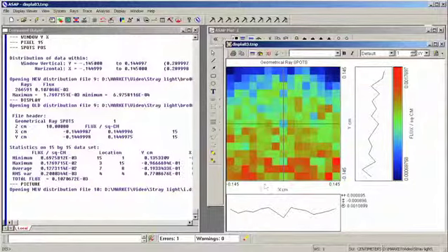Now this is our final answer, but for stray light calculations that's not enough. We need to know not only what is the stray light irradiance, but which contributors to the stray light irradiance are the larger of the two. Is it the inner conical baffle, or is it the primary mirror? When ASAP is doing the ray trace, it is keeping a partial history of that ray trace that includes most of the information about where the stray light is coming from.